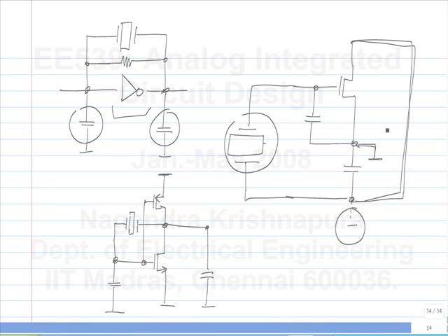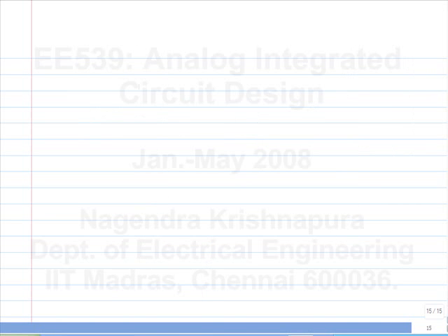If you look at old high-speed amplifier circuits, lots of them are like this, because it was quite common to use bipolar emitter followers, in fact many of them, to get very strong buffering. When you have that driving a heavy capacitive load, you will get a very high probability of instability. To get rid of that, you connect a series RC at the gate. Any questions on this?